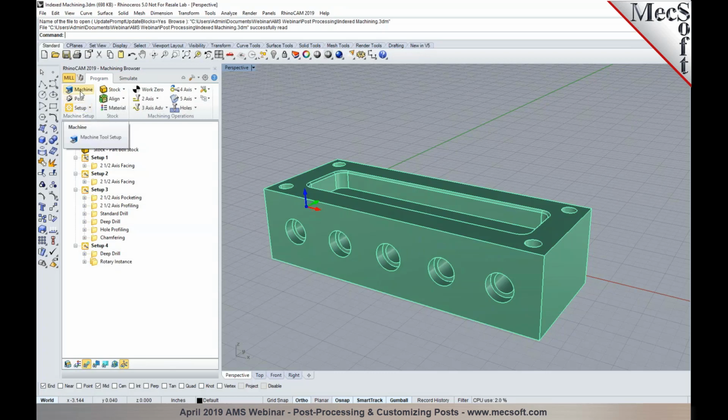So you're probably already familiar with how to define your machine tool for programming for 4-axis. Once you've done that and selected your post processor, you would be programming each orientation on a different setup using rotate table setups. If this is going to be an indexed operation, you would be doing rotate table setups. Now that you've programmed different setups, you would want to post all of them out to your machine tool. So right click and select post all.